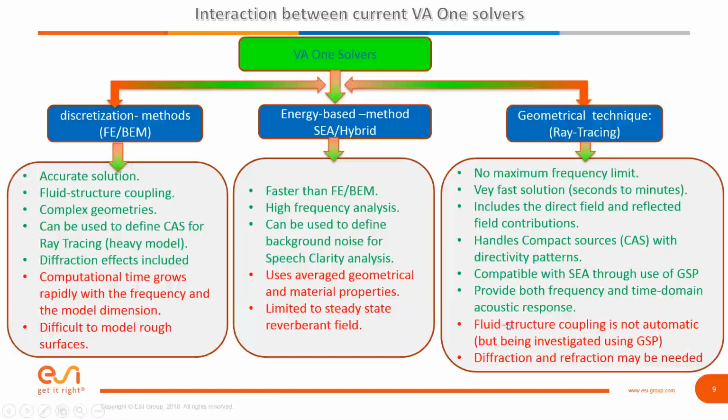What are we missing today? Well, again, we don't have this fluid structure coupling like we do for boundary element. So for coupled structures, this basically means if you expect the acoustics to excite the structures and interact and have some two-way interaction, then you still need BEM at this stage. There are some interesting things we're exploring to see if we can change that in the future, or at least work with pure SEA models and allow the transmission through the structures. But still a little bit in investigation, which means right now better for the pure acoustics problem.